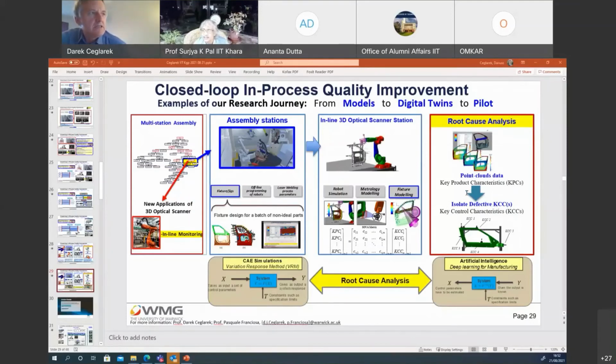Right now, the goal was not to use any filler wire, if possible. For some materials, it's doable. Not to use an inert gas, in other words. This was done by naked laser without inert gas and without filler wire for 5,000 series, which we did before. Audi also did the 5,000, so this was doable, and it is doable right now. For 6,000, we're also doing it for sheet metal without wire and without inert gas, but not for all material. For high strength aluminum, it is becoming important right now, but no inert gas can be done.